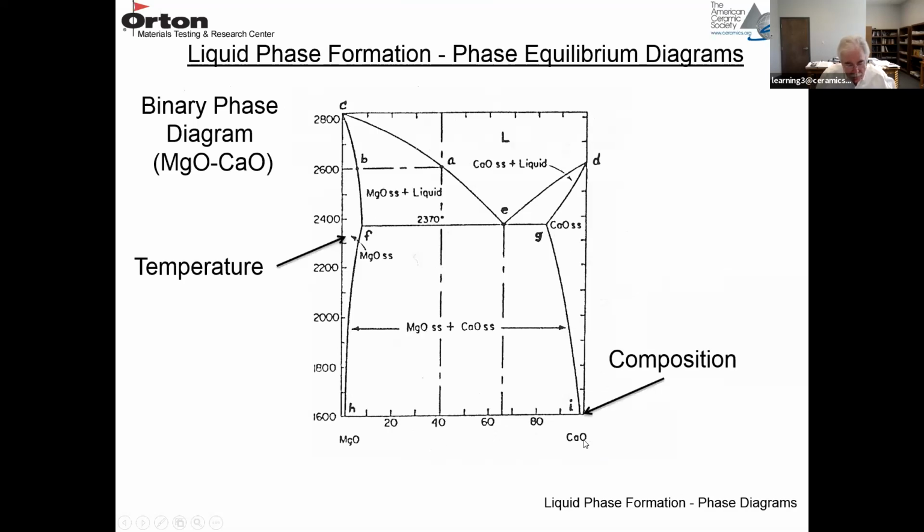So that's a little bit about wetting. It's important to remember that you want to design a refractory in an application so that whatever fluid is in contact with it is non-wetting. That's why, when we talk about composite materials with essentially a graphite matrix, metals and slags are non-wetting to graphite. So that's one of the advantages of making these composite refractories. It really cuts down the corrosion rates.